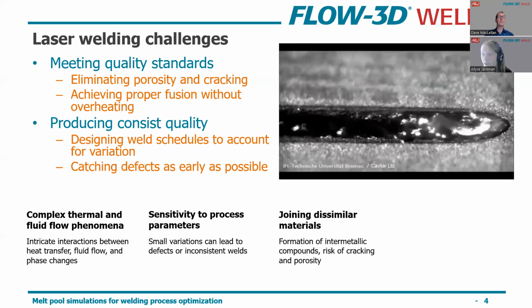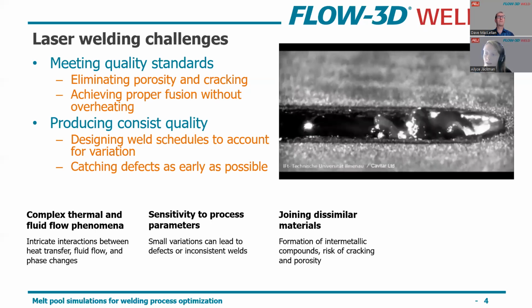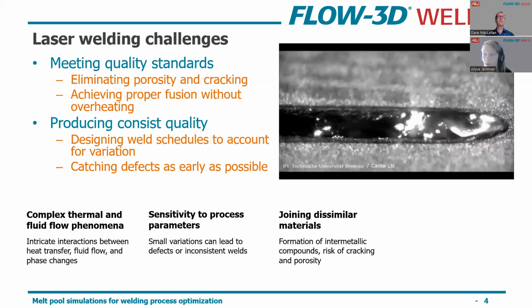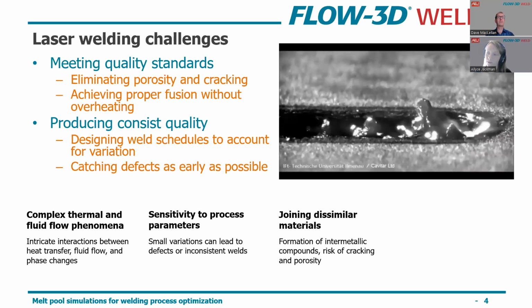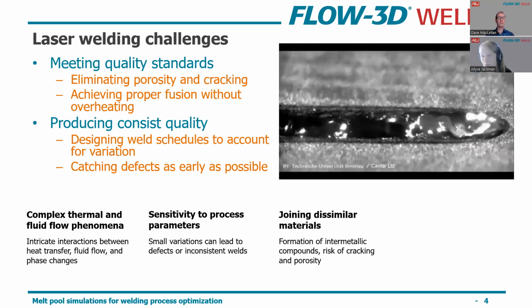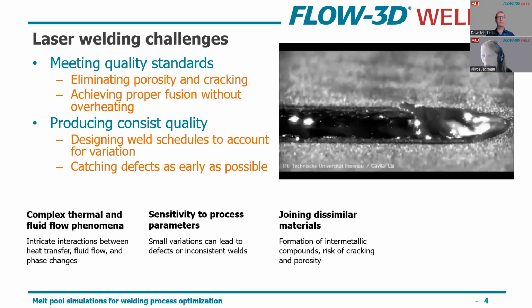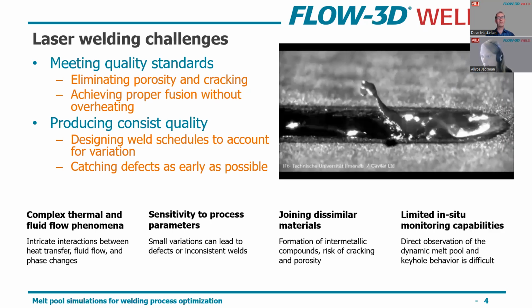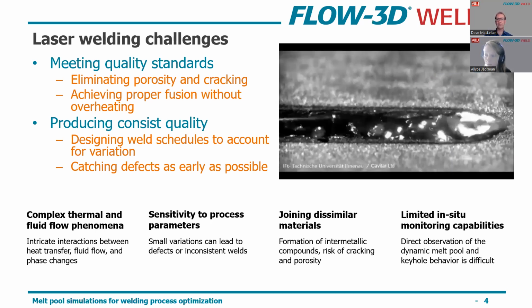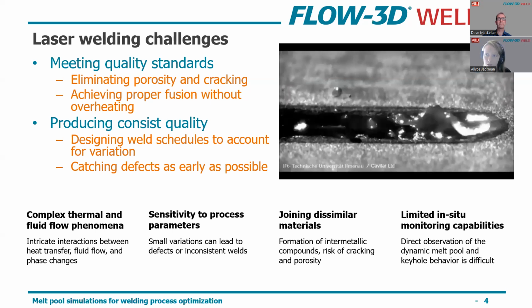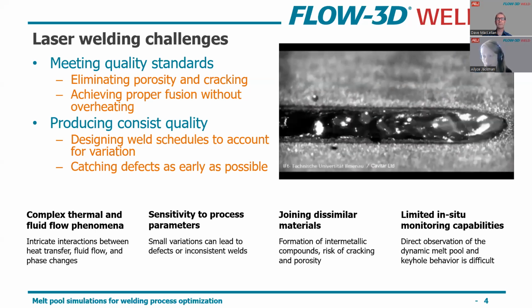And on top of this, there's a lot of applications for laser welding where they're trying to join dissimilar materials. So that creates a further complexity where you have the complex fluid thermal phenomenon of 2, or maybe 3, independently defined alloys. So there's limits in terms of the experimental capabilities to really monitor the influence of the process parameters in this situation.